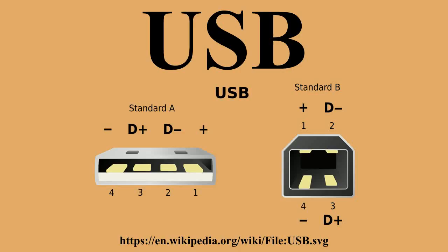An exception to this is endpoint 0, which is used for device configuration and is not associated with any interface. A single device function composed of independently controlled interfaces is called a composite device. A composite device only has a single device address because the host only assigns a device address to a function.